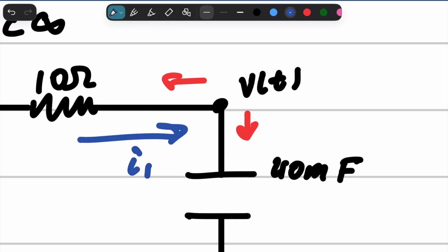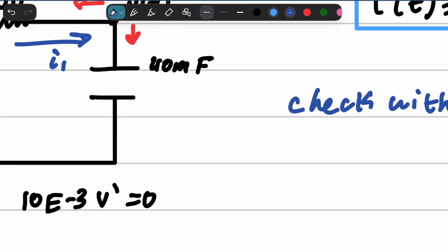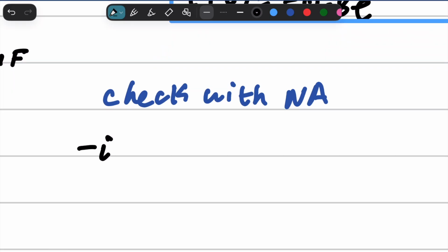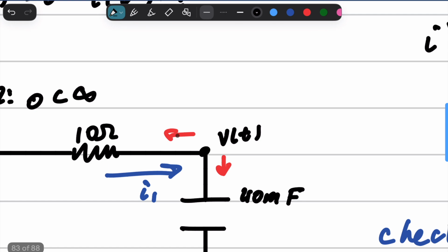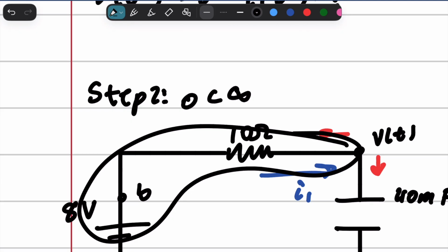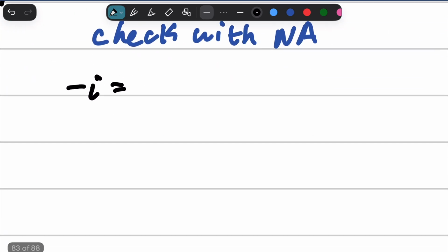So we're going to say that because we've defined this I1 as going into this node, the I that we found is automatically negative I. And the reverse, the V minus, right, because we've got this I going this way, and we want to find the branch of this because it's just the same, because it's just two nodes. That's why we've applied the negative sign. It'll just be V minus 8 over 10 because we've already accounted for our physical interpretation.